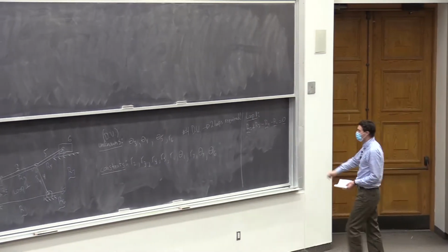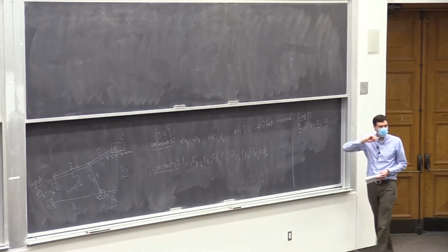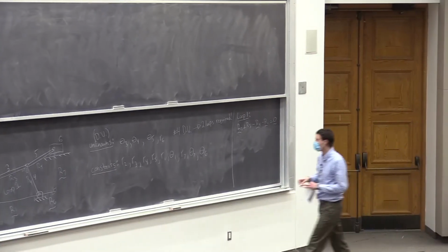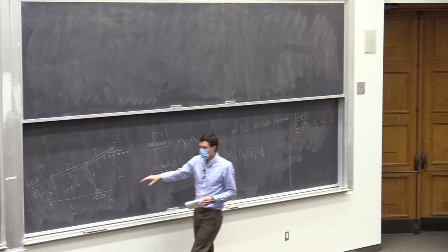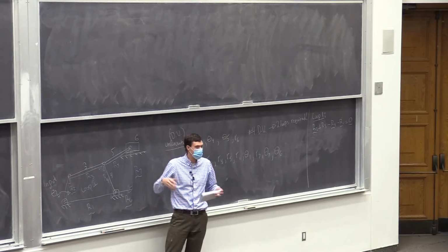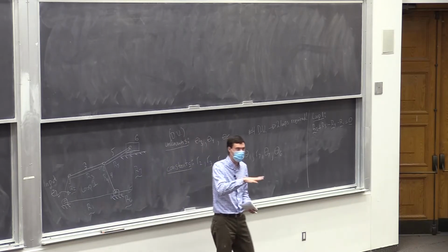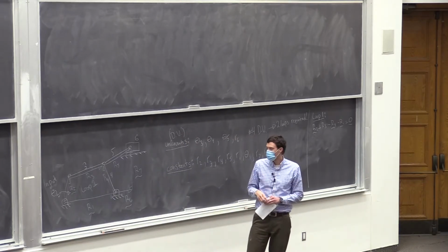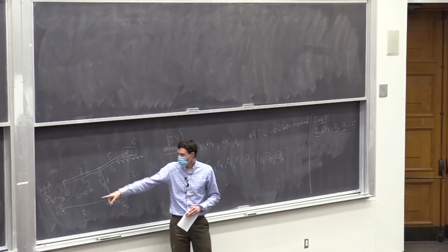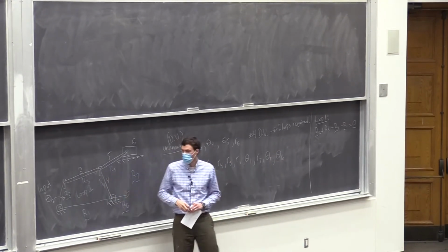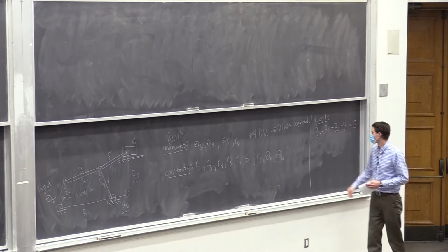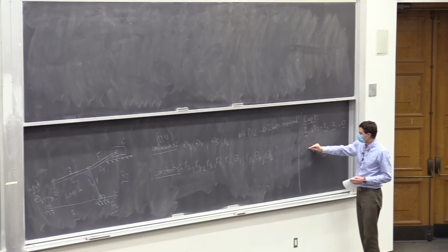And that's going to be the best trick or technique that you can use in studying more complex mechanisms, is look within your mechanism for something simpler, like a 4 bar or a slider crank. And in fact, you already will have solved those. We've already solved a slider crank. We've solved an inverted slider crank, which is like a variation on the slider crank. Next time, we're going to solve this loop 1 for a 4 bar. So you'll have that solution, and you know what it looks like, and you can just kind of crank through it really quick. That's our loop 1.